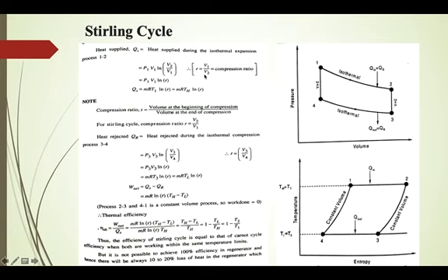actually we have a ratio known as compression ratio. Compression ratio is the ratio of total volume to clearance volume. Total volume, that is if we consider a piston cylinder arrangement over here, okay, we are considering a piston cylinder arrangement over this space. Now this is the cylinder head, this line is the cylinder head. We have a piston over here which is reciprocating or moving back in this direction, and it will move until this end. So this is the total volume. V3 or V2 is the total volume, and piston moves inwards until this point. This is the inner dead center. Let us consider this as inner dead center.